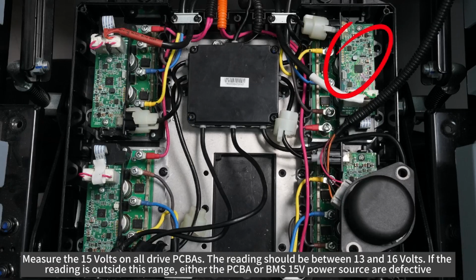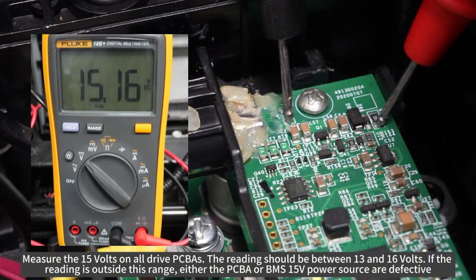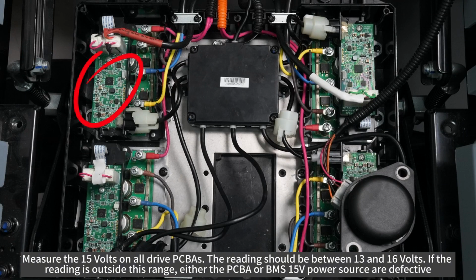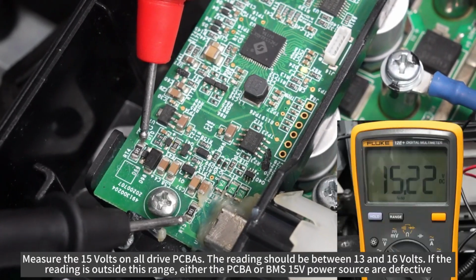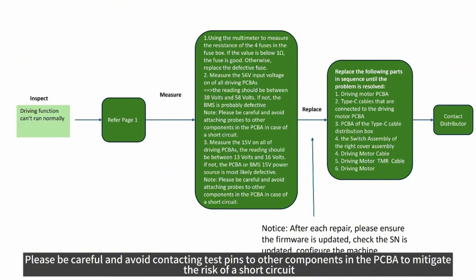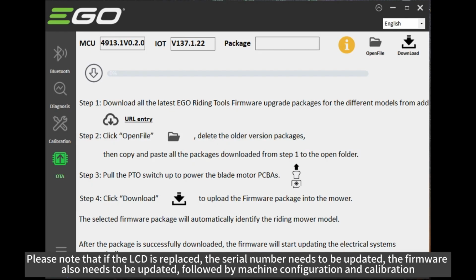Measure the 15 volts on all drive PCBAs. The reading should be between 13 and 16 volts. If the reading is outside this range, either the PCBA or BMS 15 volts power source are defective. Please be careful and avoid contacting test pins to other components in the PCBA to mitigate the risk of a short circuit. Please note that if the LCD is replaced, the serial number needs to be updated. The firmware also needs to be updated, followed by machine configuration and calibration.